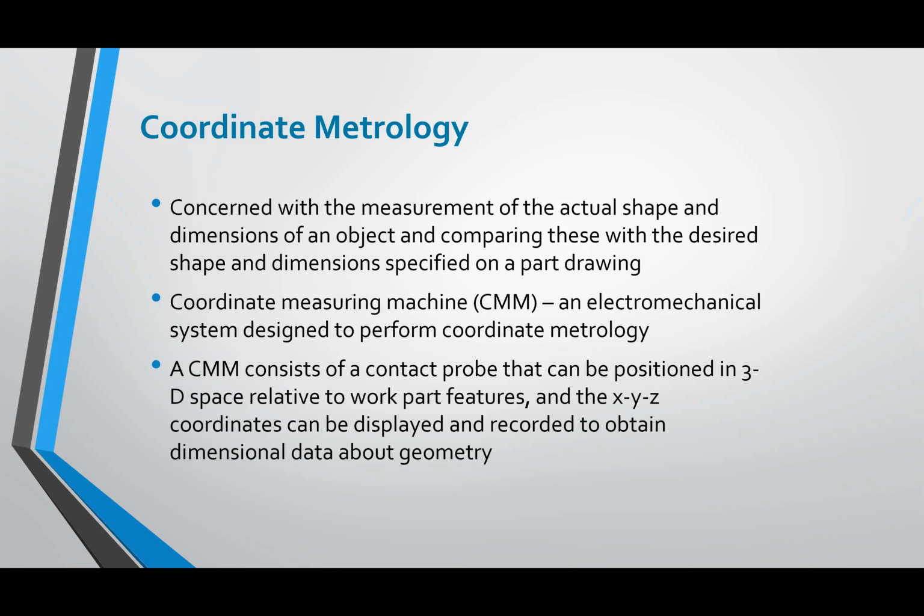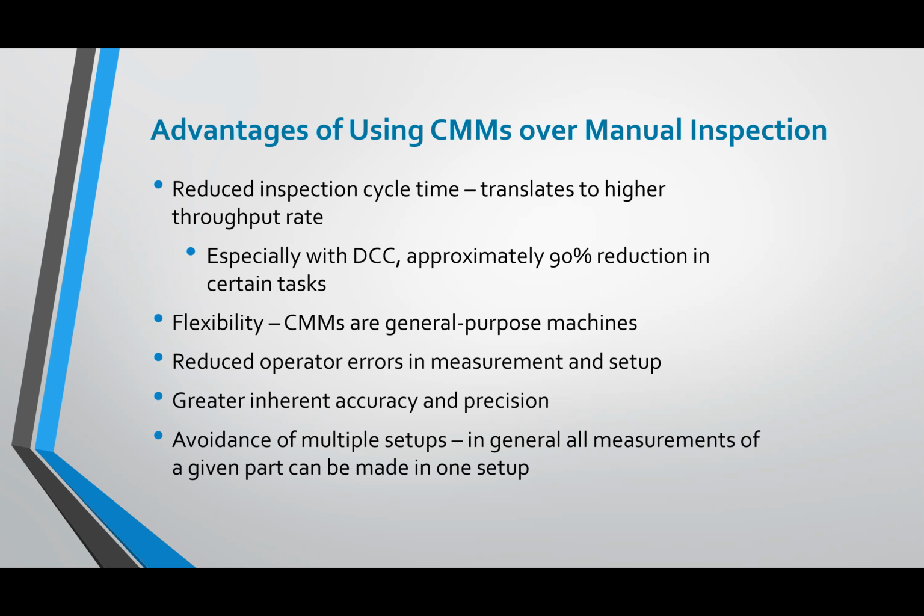to the computer drawing. And so you have a much higher level of accuracy and precision, as well as being able to complete all dimensions of the part very, very easily. And all the person has to do is load the machine, unload the machine, and verify that the drawings were correct. So when you look at using CMM machines, again, it reduces the cycle time, so you're able to inspect more things faster. The CMMs are able to measure any device.